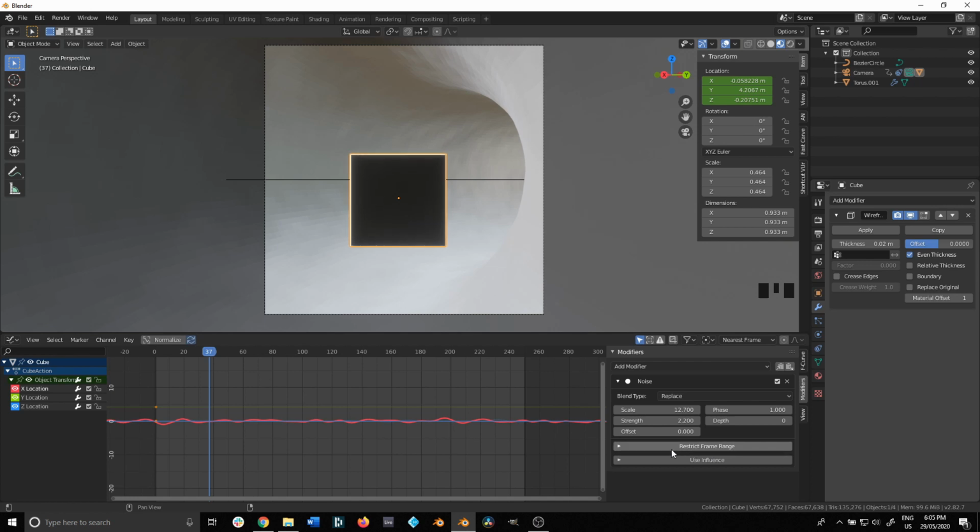and the way to make this loop is just come down to the restriction frame rate, the range, and let's just turn the end frame up. So what this does is it adds a bezier to the start and the end of it. So I'm going to give it a bezier of 10 frames on either side, and I'm going to do the same for the z-axis.